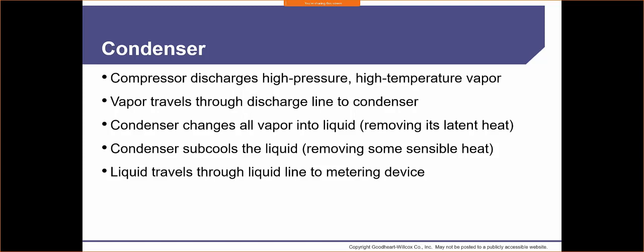The opposite of subcooling is superheat. If I have 70 degrees, and we're talking about a vapor at this point, my saturation point is 70. Now all of a sudden I'm at 80. Well, I have 10 degrees of superheat. Why is that critical? I have a 10-degree buffer before my vapor will turn into a liquid.